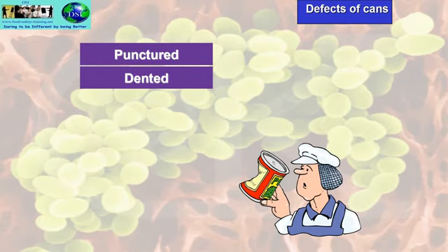A metal can, which is either aluminium or stainless steel, has a protective plastic coating on the inside. And if a can is dented, then this plastic coating can become fractured on the inside and let the food come into contact with the metal itself. Not so much a big problem with stainless steel, but certainly with aluminium it could be, especially if it's acidic food.